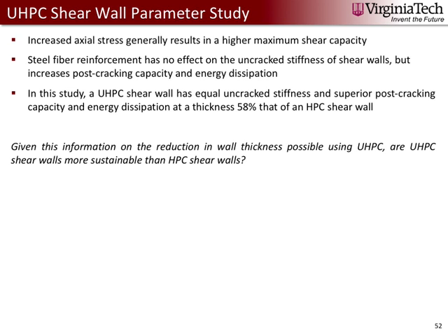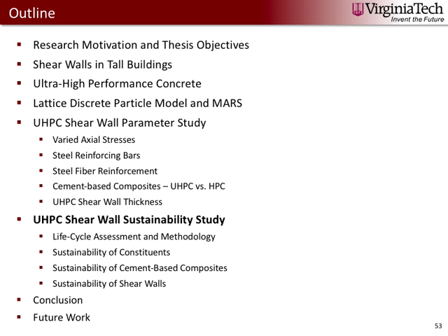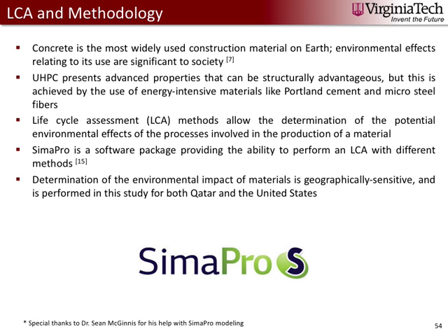So given this conclusion in the reduction in wall thickness possible using UHPC, is the UHPC solution actually more sustainable than the HPC solution? And that's what we're studying here. So to answer this question, we've used a life cycle assessment approach. UHPC, again, presents advanced properties that can be advantageous for using in structures, but it does so at the cost of using energy-intensive materials like Portland cement and microsteel fibers.